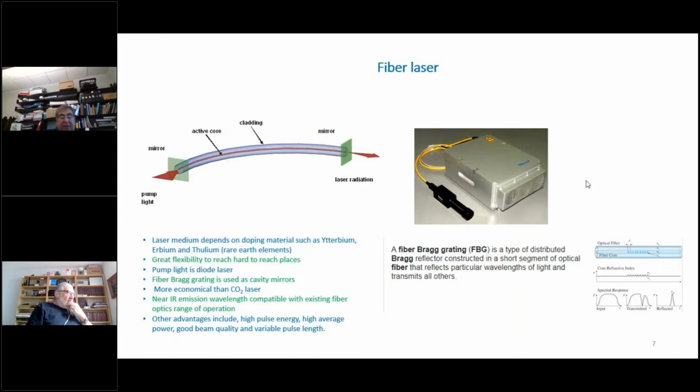The fiber laser has many advantages simply because it doesn't use mirrors on either side of the cavity like the normal lasers. In any cavity there are mirrors. Here there are some scribing inside the fiber optic that acts as a diffraction grating and only reflects one wavelength.